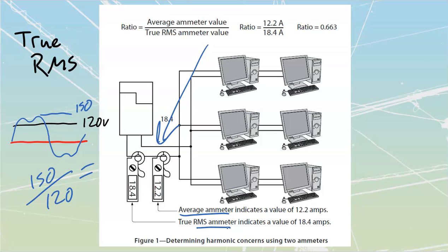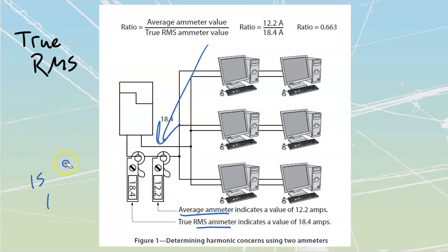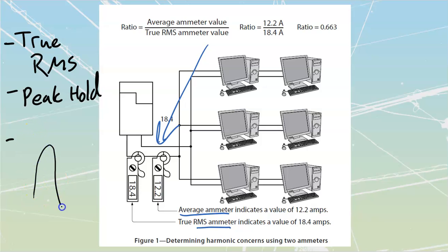So yeah, you need peak on your meter. If you don't have a good meter, the stuff you should be looking for is, if it can do crest factor alone, that's great, but you want to have true RMS and you need to have a peak hold as part of it, as well as the smallest sampling time, where it's going to just grab this and be able to see a whole waveform. Some of them only take a couple samples in a second, which is going to be really hard to get a good average off of. You want to have a high sample rate inside of these.